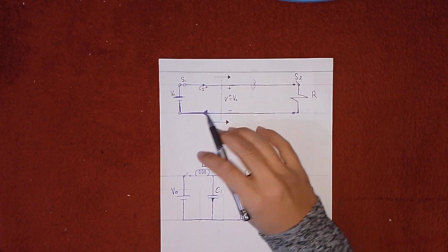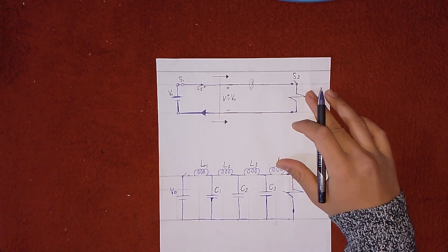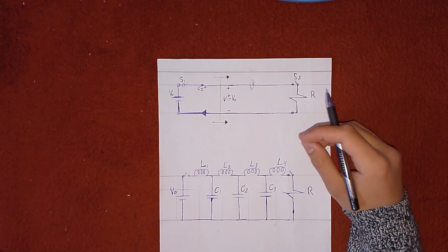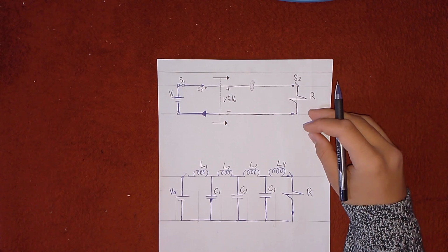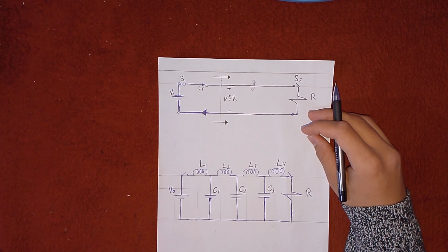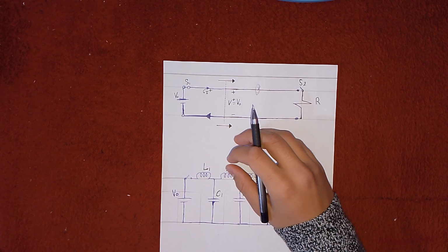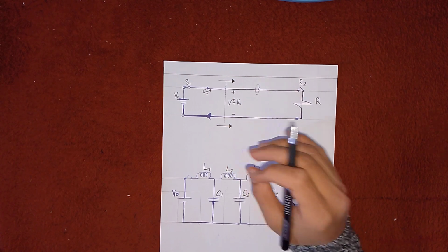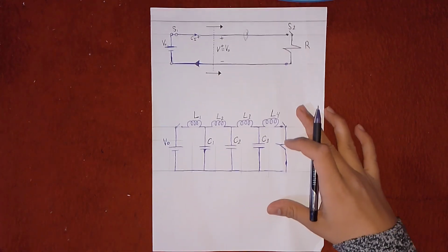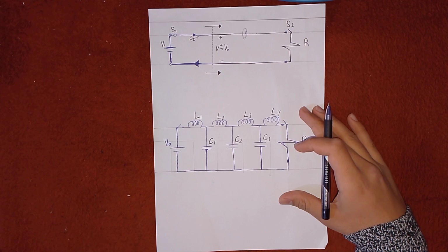And since the transmission line is very long, the capacitance and the inductance are distributed continuously along the entire length of the line. And instead of writing the total capacitance or inductance for the whole line, we express them per meter or per unit length to simplify the analysis. So the conducting transmission line will possess capacitance and inductance that are expressed on a per unit basis. Thus we can construct a model for the transmission line using lumped capacitors and inductors as shown here.